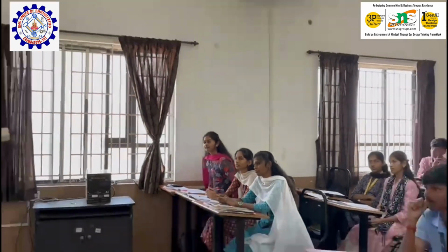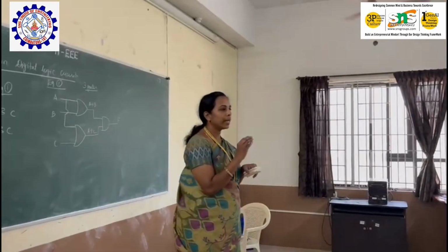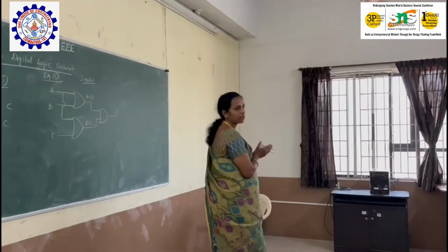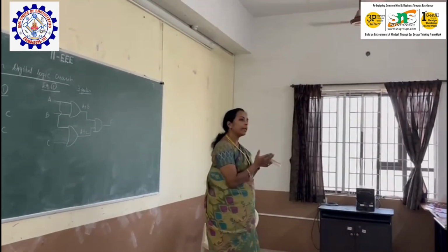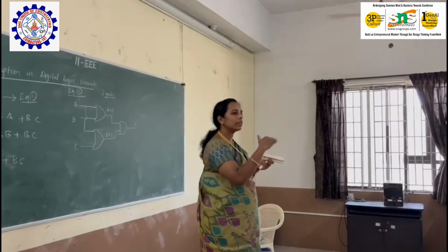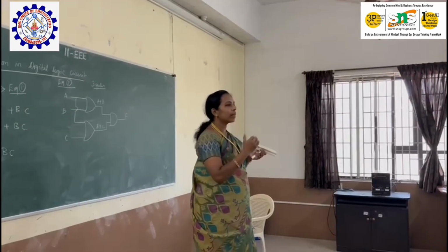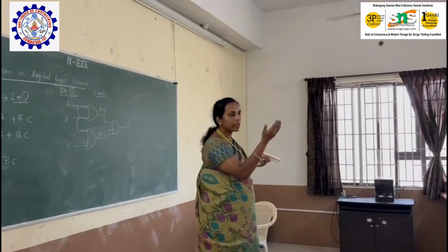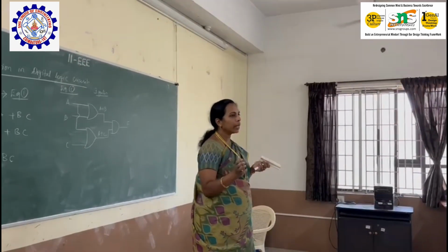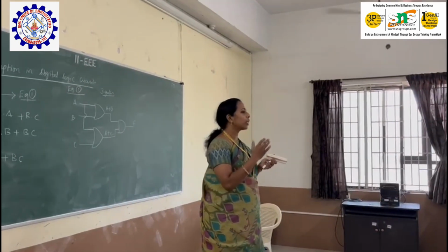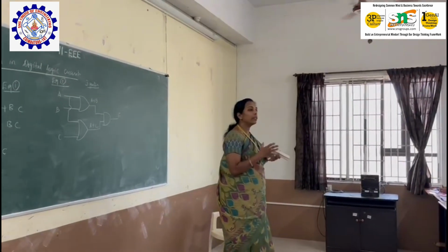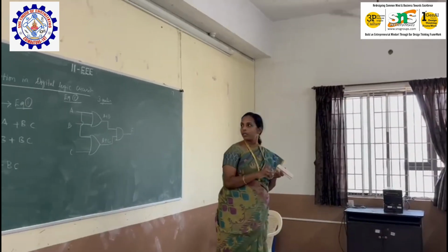Yes. As I already showed in a video, every gate has transistors, right? Inside the transistors there will be parasitic capacitance, and what happens when a transition from 0 to 1 takes place? The capacitance is charging and discharging, right? When the transistor is in one state, the capacitance is charging. When it is in the 0 state, the capacitance is discharging, right? So every time the capacitance is charging and discharging, it obviously will consume energy, so power consumption will be there.